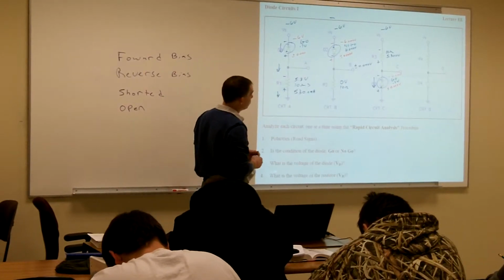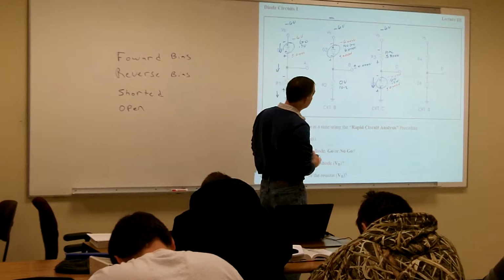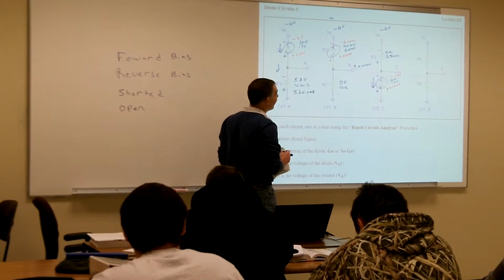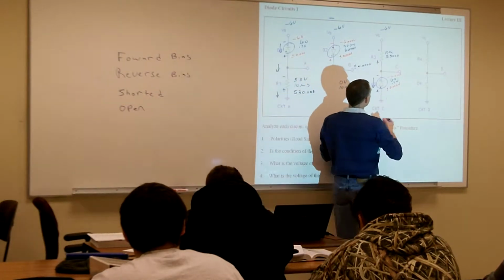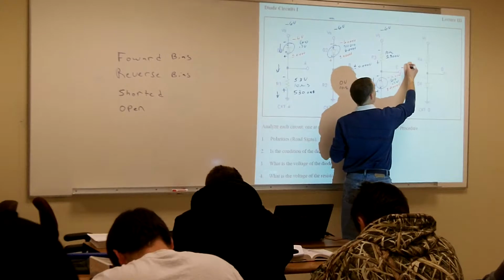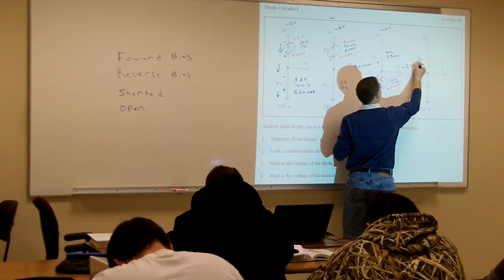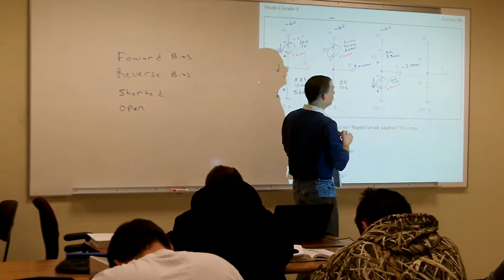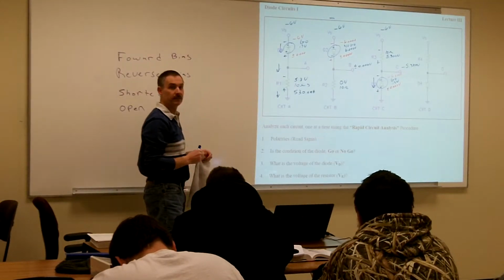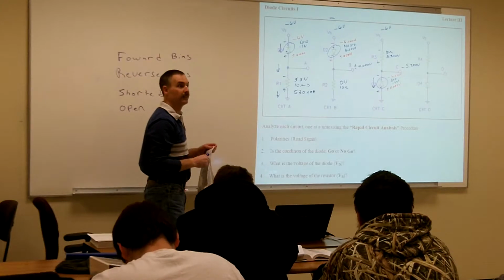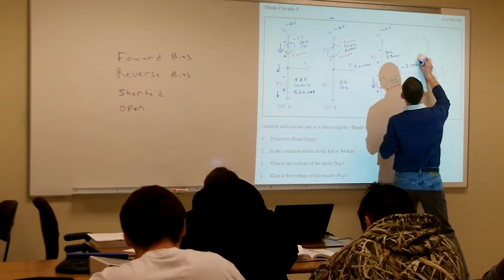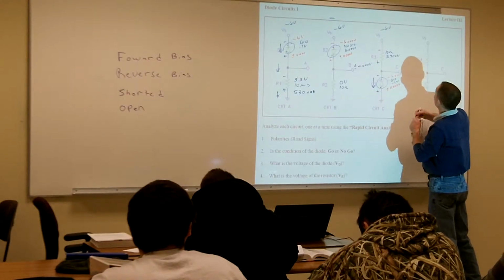A major amount of the voltage. So then my voltage at my test point is going to be what? 0.7, isn't it? Negative what? Negative 5.3. Everyone agree with that? Wouldn't it be 0.7? Because we're measuring across the diode, so that would be a negative 0.7 volts.